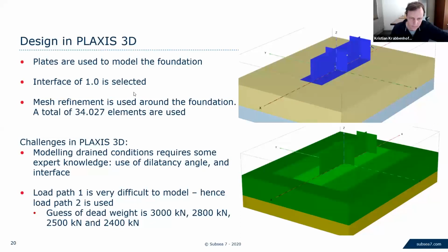When you use elastoplastic analysis, there is the need to somehow select some elastic parameters, whereas with limit analysis, it's only the strength parameters that are in play. Exactly. Particularly in the case of the counterweight, the displacements really don't matter. If this has displaced 20 centimeters, it would still have worked just fine. It's really the capacity that we're looking for in this case.